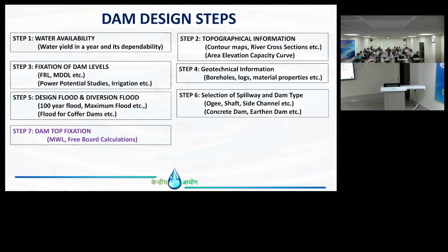You can maximum allow only this much spillway. If the inflow flood is, let's say, 10,000 cumecs, here you are able to provide 10,000 cumecs of spillway capacity, but here you cannot. Here suppose, let's say, 5,000 only. Let's say you are able to pass only 5,000 cumecs from the spillway. So what about the remaining 5,000?